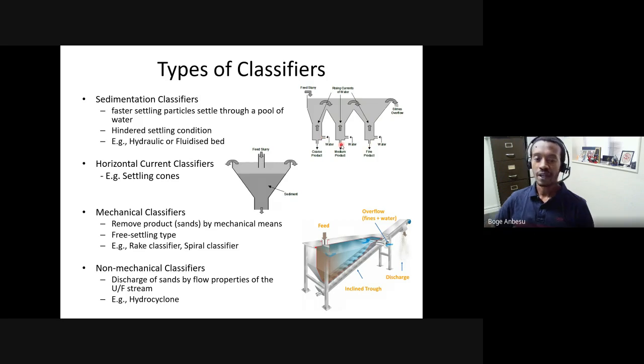So essentially you could have a number of these cylinders one after the other and classify particles based on their size. You can also use density if that is what you have in your operation. So if particles are the same size, but they have different densities, then the same principle can be used. In this case, the densest ones will fall first and be collected in the coarse product, and then you have medium and so on. As you can see here, the cylinder gets bigger and bigger, obviously, because every time you go to the next cylinder, you introduce more water. So you have to allow for that additional water being introduced, and therefore the capacity of the cylinder needs to be a bit bigger.